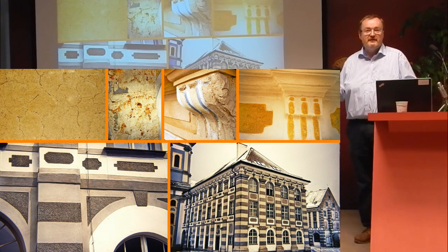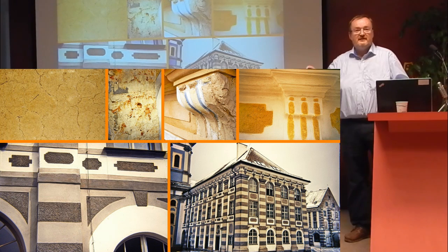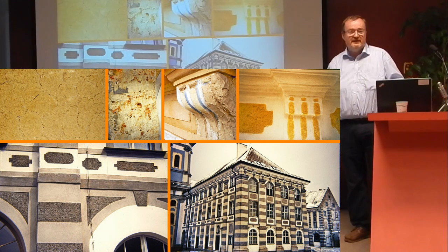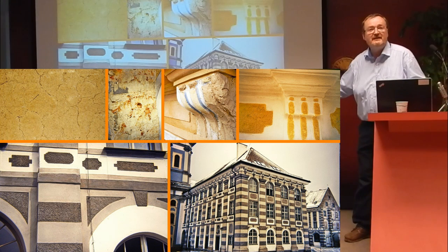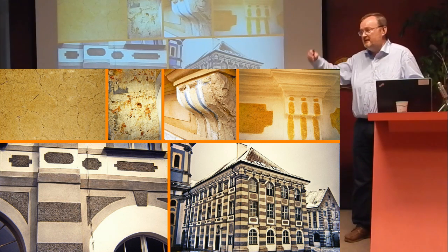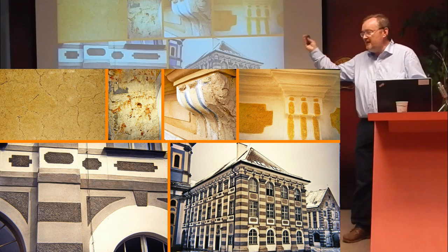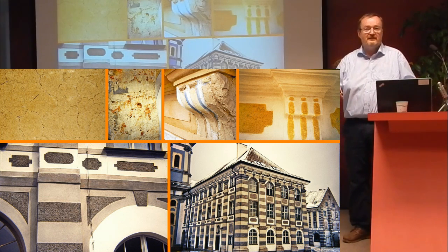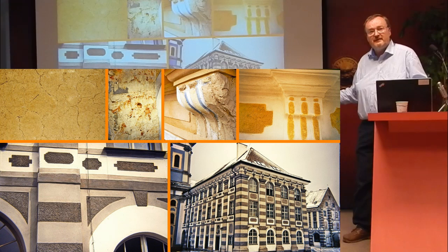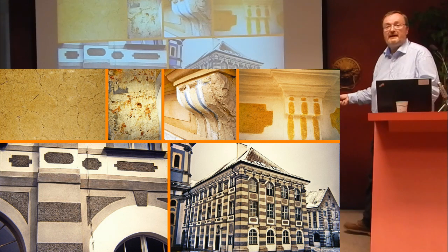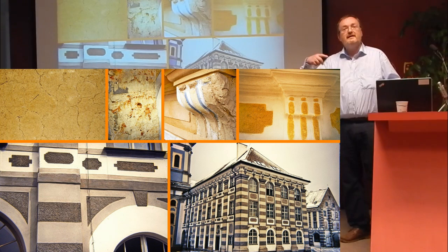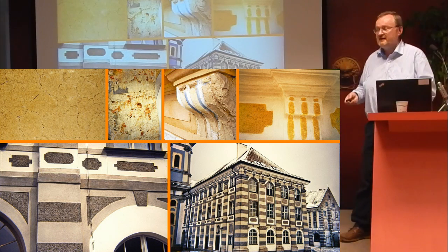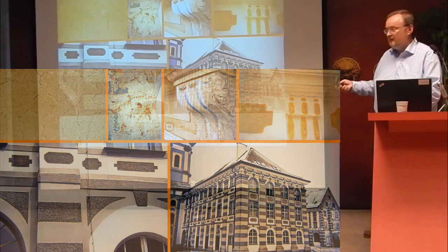It is cheap and you can buy it everywhere, but the craftsmen will not trust it because they no longer have the know-how to manage the binding of the lime, and it will chalk down, like sand or like chalk or like rain. The art of the craftsman is to manage the binding of the lime, so that the reaction of carbonization works. That's the only secret. But few craftsmen know this.